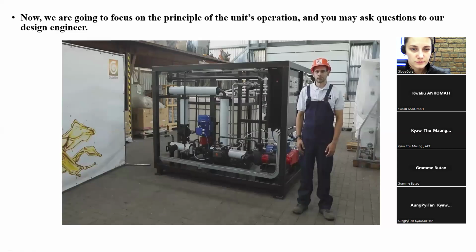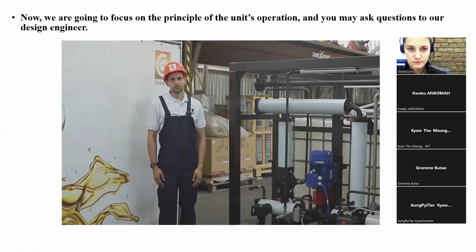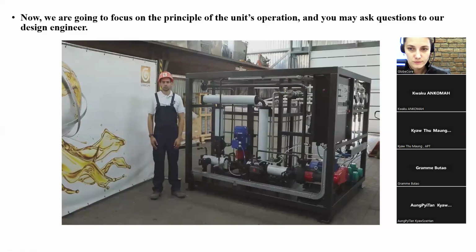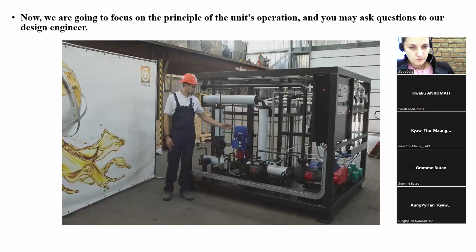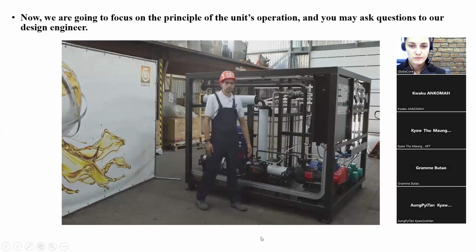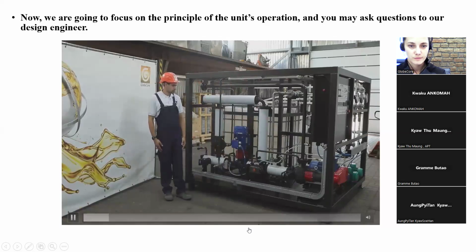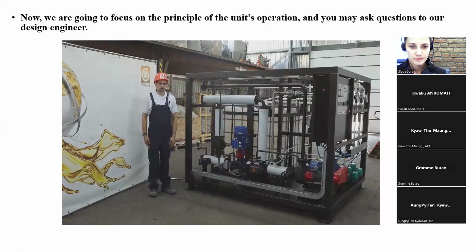This unit can be conveniently divided into 2 parts. These include a water phase preparation section and an emulsion preparation section. This unit is assembled on a frame. Consists of the following components and assemblies. The emulsion preparation section includes a bitumen supply pipeline, a pumped assembly, a bitumen mixer, and a colloid mill. The unit also includes a bitumen return pipeline.